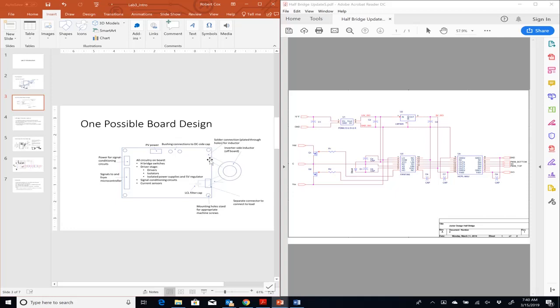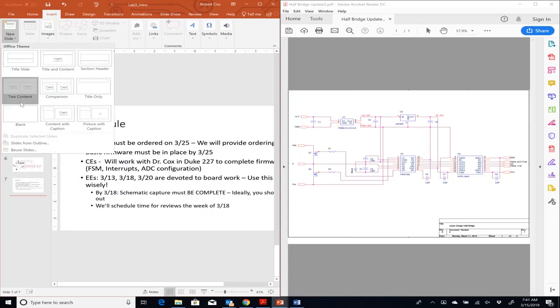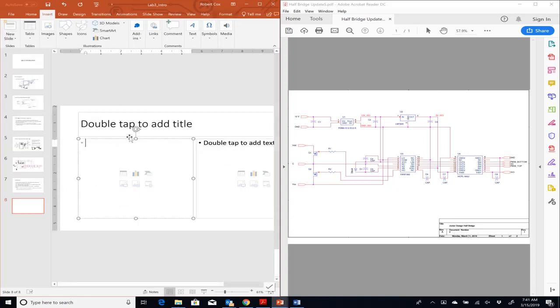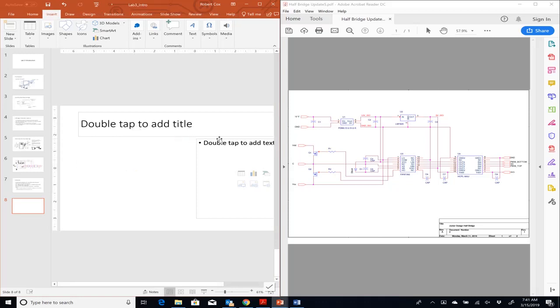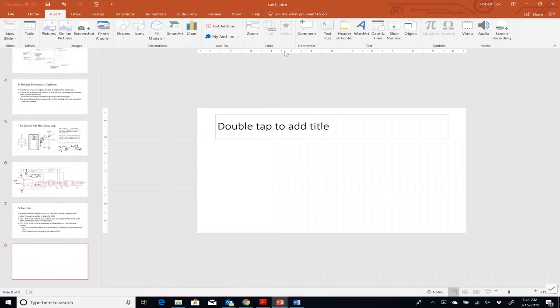If you watch the video and look at the lecture notes on the full bridge and how we use it, what we said is we use 2 inductors in series. There are actually 2 inductors on here. So we have 2 wires going to the inductor and 2 wires coming back. Effectively what we're trying to implement is this: L, capacitor, L, and this is L over 2. This is L over 2. So this is to one midpoint, and this is to the other midpoint. This point and this point go back to the board.